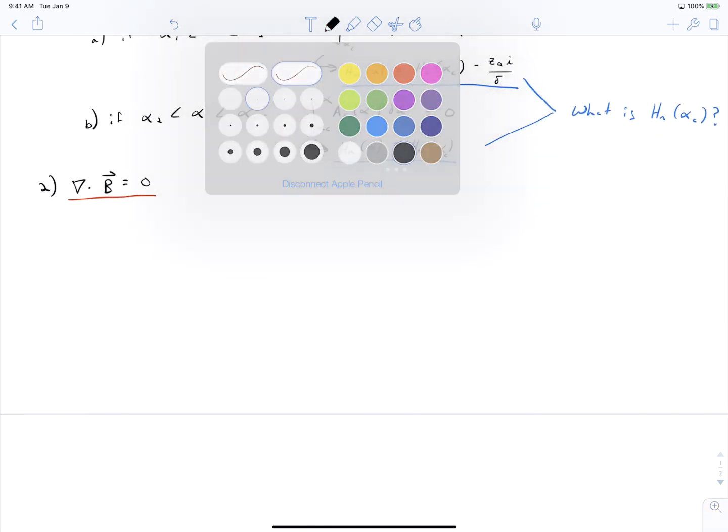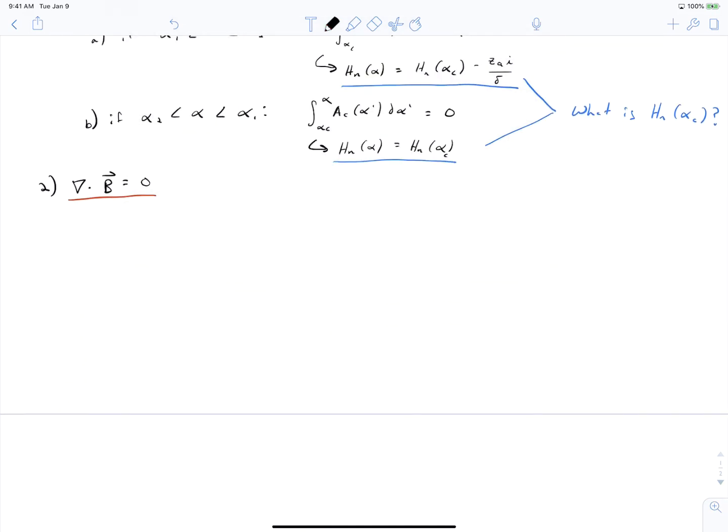And for our purposes, we want to express this in the integral form, which is that the integral of H over all surfaces needs to be equal to 0. We can't have any net source of flux. You have to have flux in closed paths. And we'll conveniently decide to do this over a cylinder in the air gap that encompasses our rotor. So we're going to place a cylinder over our rotor and impose that the surface integral of H dot ds over all surfaces must be equal to 0.